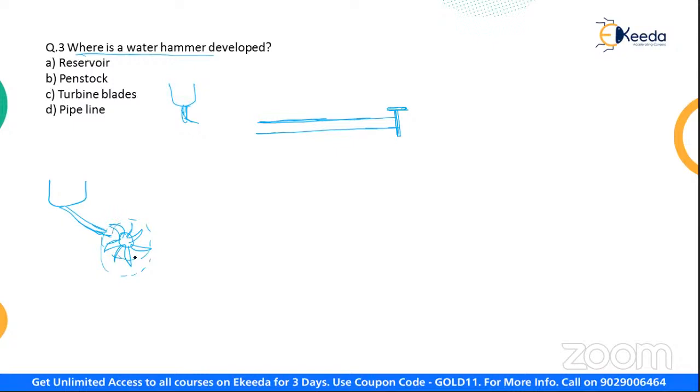Now because of the flow of the water, this turbine will be moving, because of which electricity will be generated and this will be supplied. The rest of the water that will be collected here, or the water which will be wasted here, will be further taken through this conduit, which is known as the penstock. So when this penstock is carrying the water, this is the reservoir, this is the turbine.